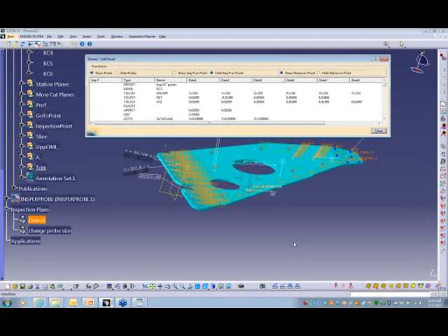Right now, this release does not support measuring planes and lines and slots and spheres. It is in the scope of things, but if you create 4 points and you're running PC-DEMIS and you measure those 4 points, you can always pull those 4 points into PC-DEMIS and construct the plane.